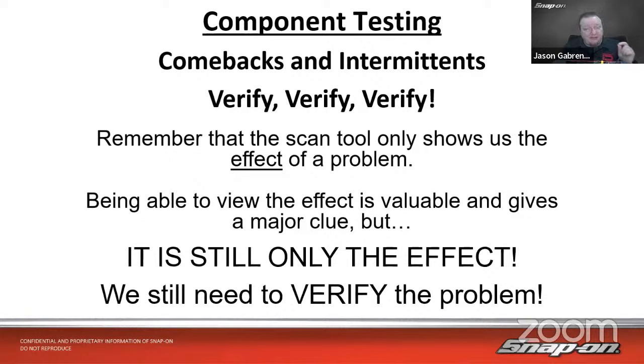If I test that mass airflow sensor and it fails the test, it is not working properly, then I can be a lot more confident in my diagnosis when I call the parts store. Then when the new part comes in, before that car leaves your site, test the new part. You might be wondering, why would I do that? Well, have you ever gotten a brand new part in a box that didn't work? Happens all the time, right?